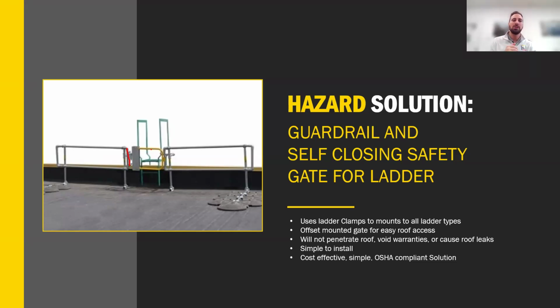Because a lot of times, maybe I've got a stair tower to the roof or an internal penthouse to the roof that's safe, but then I have to go roof to roof to roof and I have unprotected fixed ladders along the way. And then think about your work platforms inside the facility. Do they have chains at the top of them? A lot of them probably have guardrails, but no gate. So think about those as well. And if you have a question that comes to mind, throw it in the Q&A. We'll try and get to it later on.